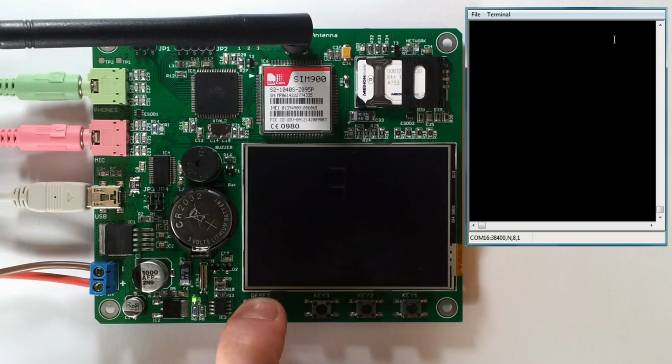So I initialize the display and you're gonna see a splash screen, and at the same time I initialize the UART, so it's gonna start talking on the USB, and then it will switch the power on for the GSM module, and it sends the GSM initialization commands. Also watch the network LED, because it will blink fast, and once it blinks at a slower rate, that will be the indication that the system has successfully authenticated and is registered on the GSM network. And here we go.